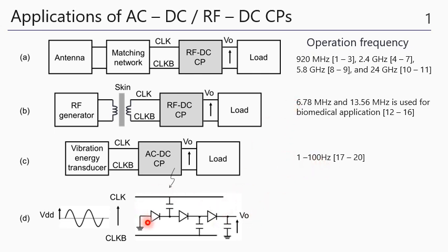The AC-DC charge pump looks like this, and as you see, the AC-DC or RF-DC converters have the same circuit configuration, but with very wide frequency ranges. Therefore, to design the AC-DC or RF-DC charge pump, a unified charge pump model is required for the wide frequency range.